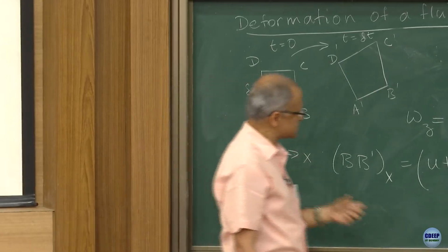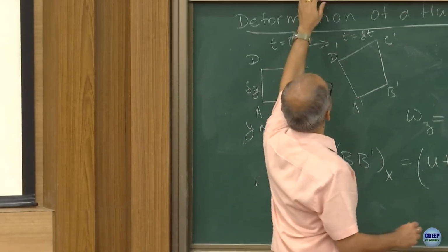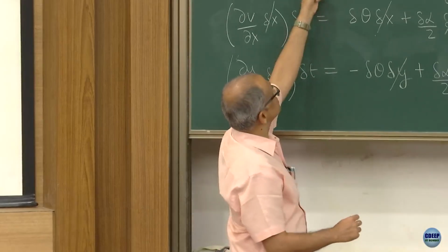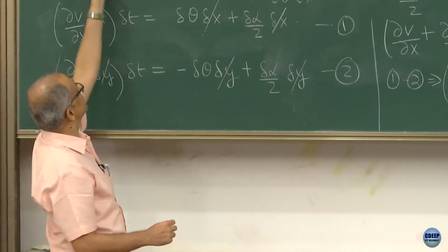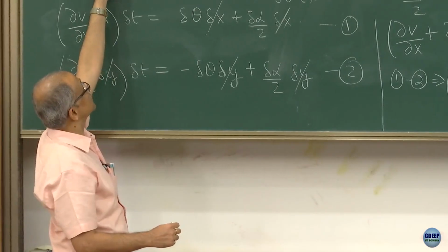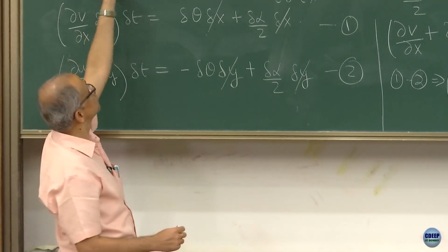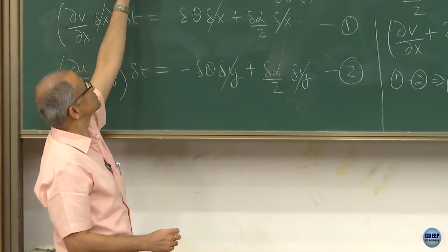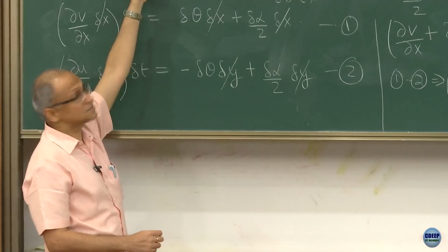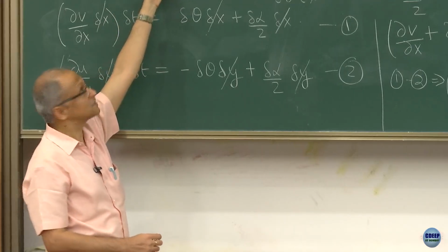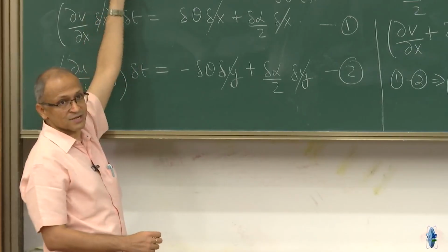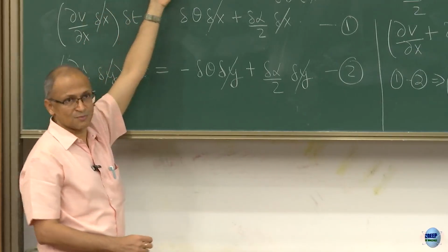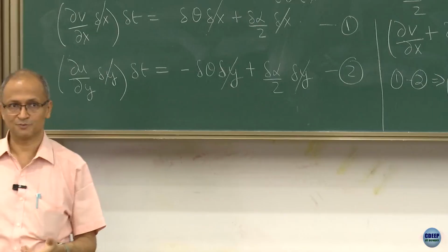Now the other thing we said is that dilation is going to happen only if the velocity at this point along the x direction is more than the velocity here. That is my component dou u dou x, multiplied by delta x. That is the extra velocity that I need to have here, and of course that multiplied by delta t, because we are looking at displacements.